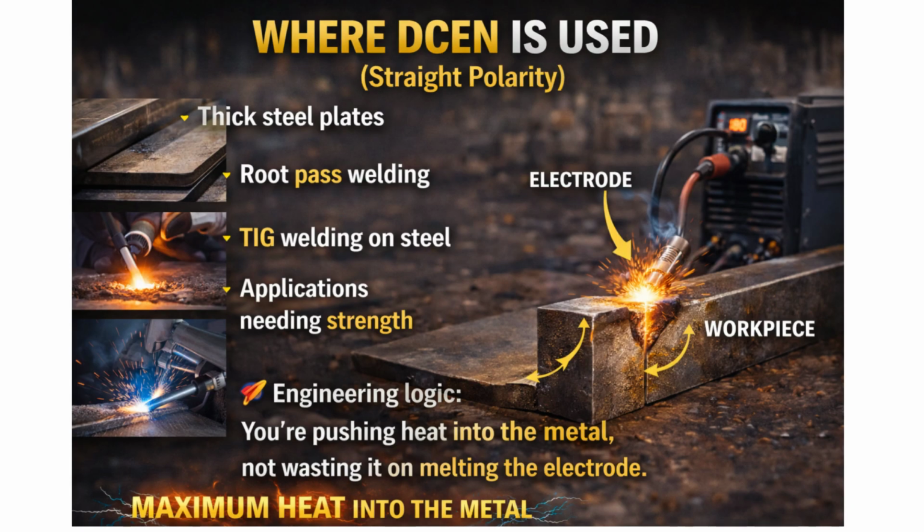Where DCEN is used: thick steel plates, root pass welding, TIG welding on steel, applications needing strength. Engineering logic: you are pushing heat into the metal, not wasting it on melting the electrode.